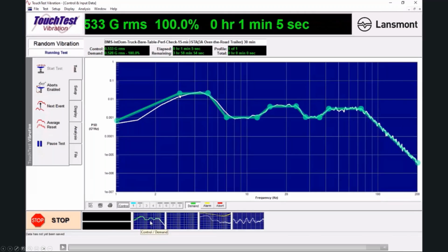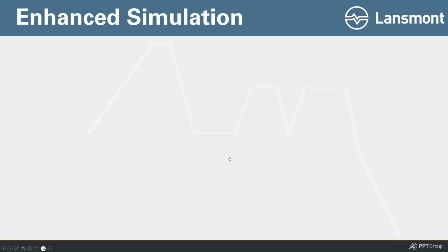But on average, that calculation is made over, in this case, like 1.5 seconds, and that average better be here. So we allow it to move in reality through, again, standard random vibration control. We allow it to move around that average, plus or minus, but at any given time, the average intensity better line up on the boundary that we set with our PSD profile, drive profile, okay?